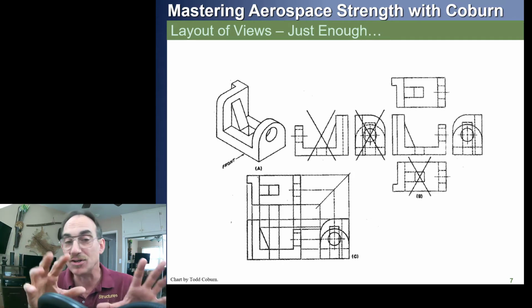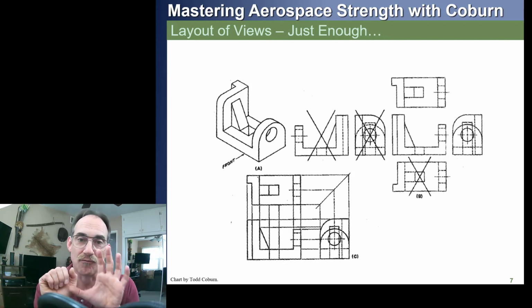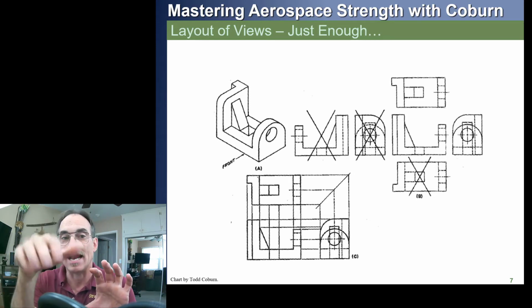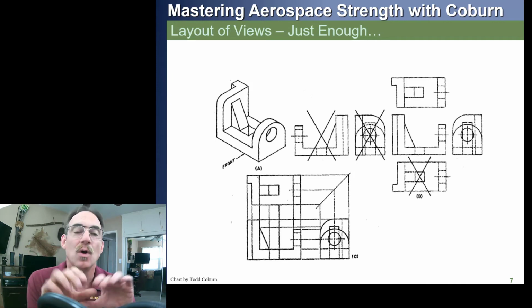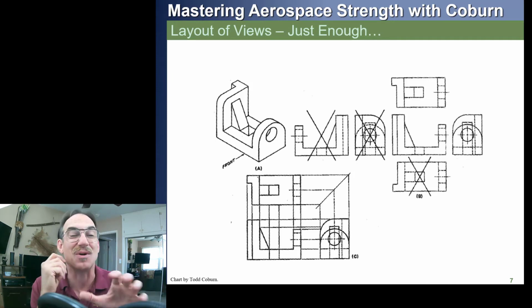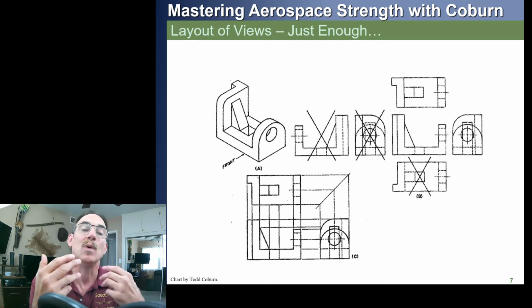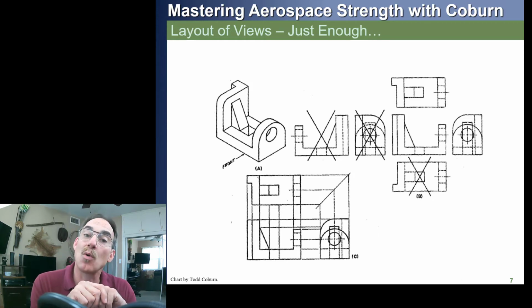So we'll often try and orient our part to select those, but sometimes the front view choice will define how we roll that out, just a right and a top view. It's more common to show the right and top view with the front view rather than the rear and top or rear and bottom. So often we break that rule, if you want to call it that, in order to show more of a standard set of views.